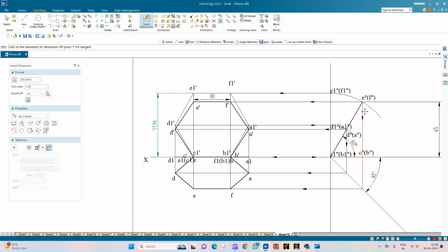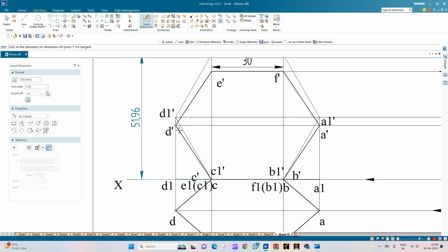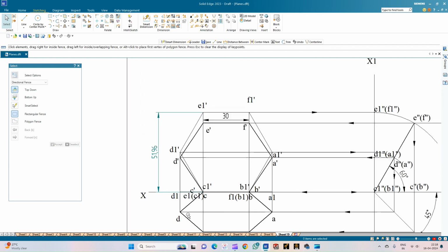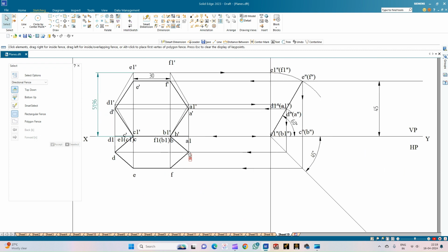And then after the side view is drawn, we are going to do the reverse position. That is, from the side view, we are going to mark the projection lines in order to get the front view. So we are going to draw a median line of 45 degrees, draw the projection lines, intersect that median line, and from that point of intersection, draw the horizontal projectors, and take the vertical projectors from the visible lamina, that is the actual lamina, that is A dash, B dash, D dash, and draw the top view of the lamina A, B, C, D, E, and F. So mark all the points, all the corners A, B, C, D, E, F from the respective projections from the corners A dash, B dash, C dash, D dash, E dash, and F dash.